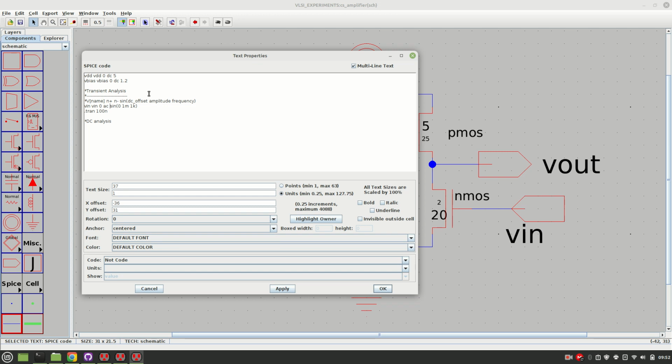So yeah, exactly, V in 0, and here the type. Okay, V in, n plus, n minus, and here is the type. That means whether it's the AC or the DC voltage. Then we are giving the sine, the sine command. So don't confuse between that pulse command and this sine frequency.